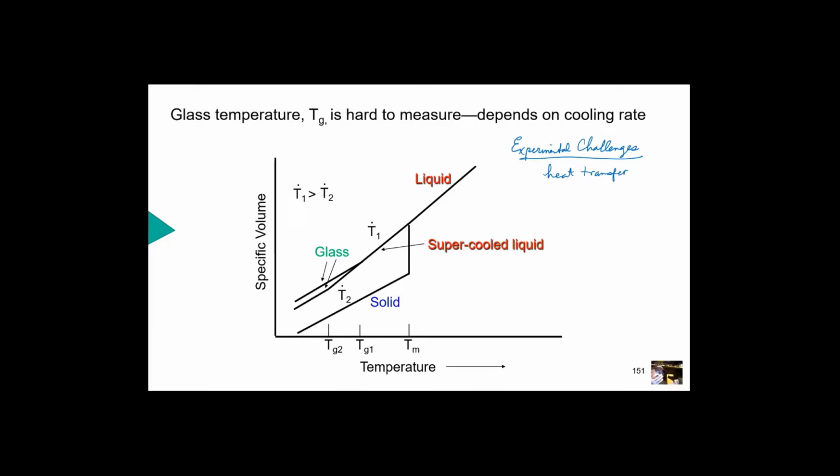So I can have a system, and I can take a chunk of polymer and I can put it in a fluid, and I can cool that fluid down. But the one thing that's difficult to do is to bury the thermometer right in the middle of the chunk of plastic. Usually we don't do that, okay? Because usually the chunk of plastic is like a millimeter big or a couple millimeters big. So there can be kind of a lag between the reading of temperature that you make and the actual temperature inside the polymer.